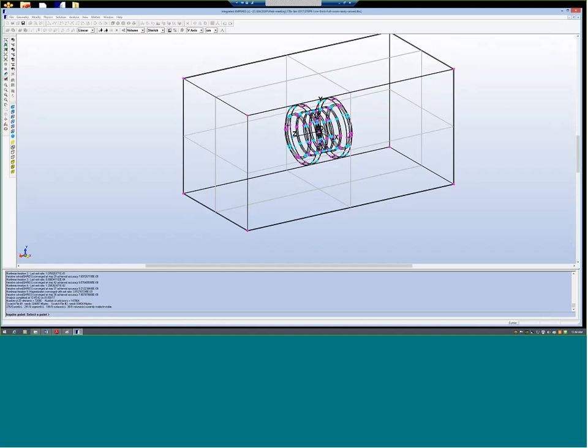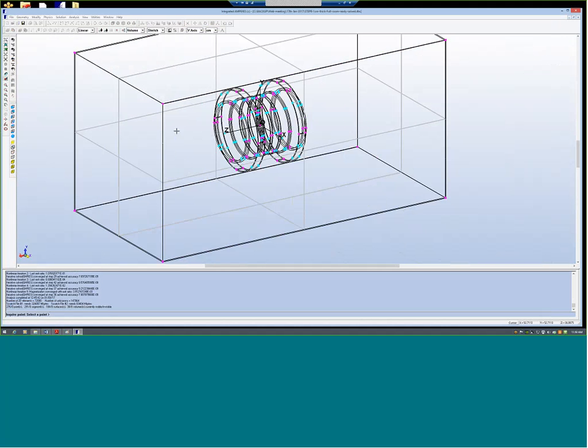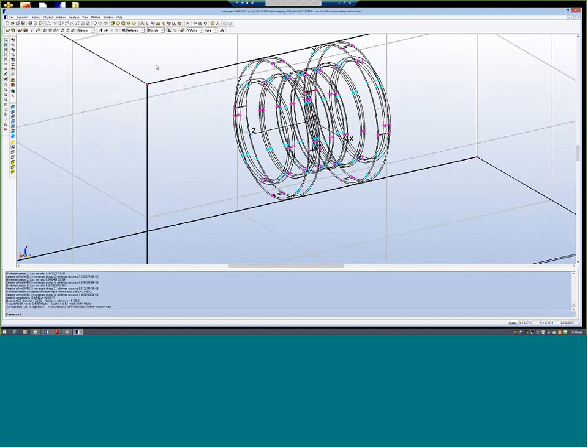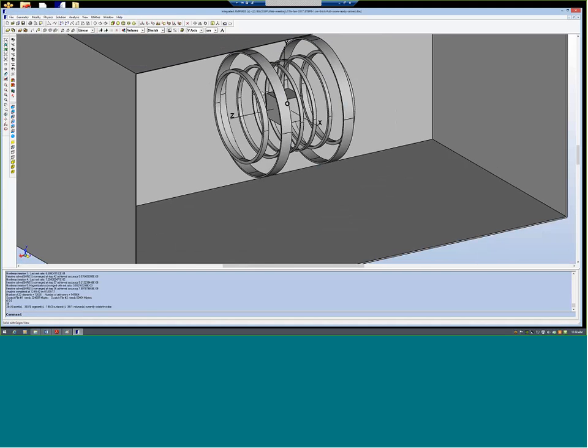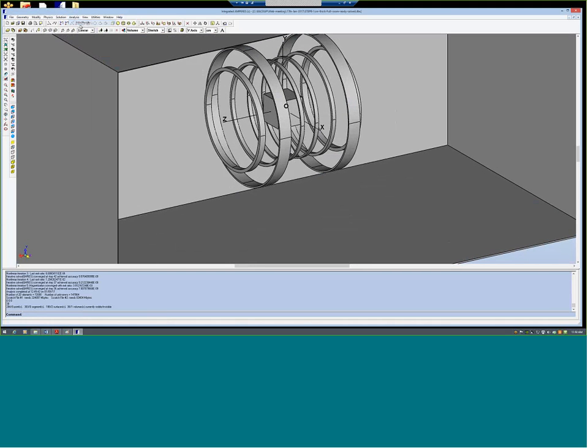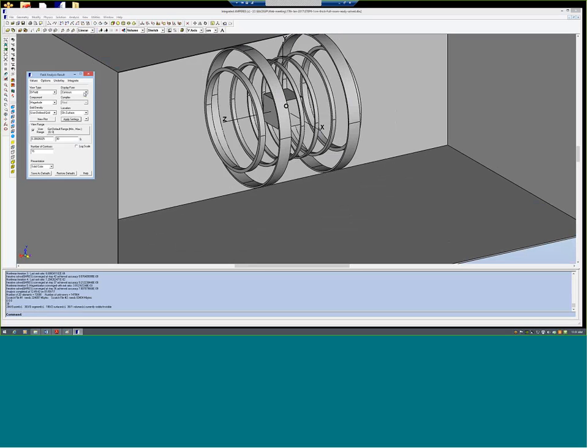Let's see what the change in the fields is at the center by putting a steel room. There will be some change. Let's take a 0, 0, 0, 30 centimeter cube. In that cube, we will hide one of the side walls, then we can see it better. In this analysis, fields, calculate, make it the z component fields, not the user range. Let me make a scatter plot.